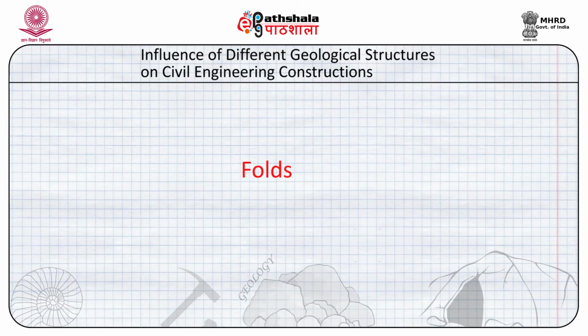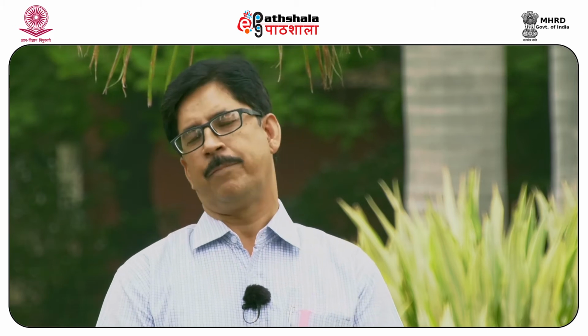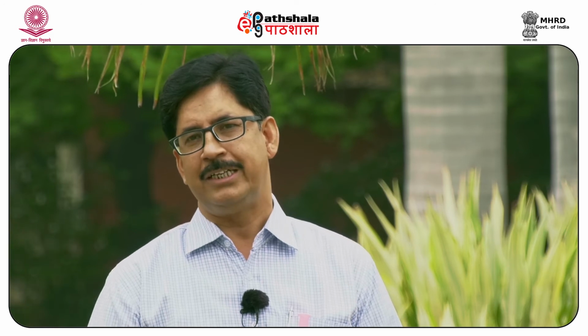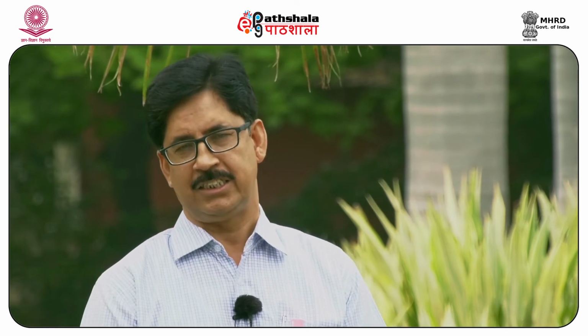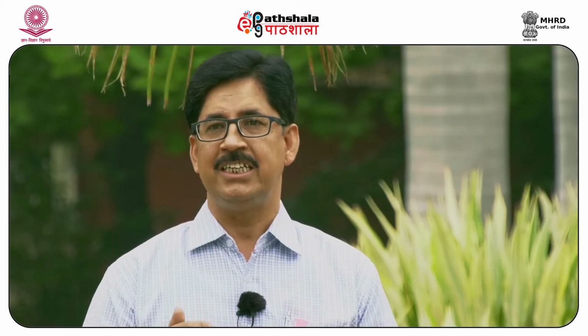Now, the fourth very important structure is fold. The folds are the result of ductile deformation of rocks, and when the rocks undergo ductile deformation, they are thrown into anticlines and synclines. The dimensions of these anticlines and synclines may vary from a few centimeters as far as their wavelength is concerned to hundreds of kilometers. Now, it all depends on what the length of your civil engineering structure is, and how it is going to accommodate these anticlines and synclines.